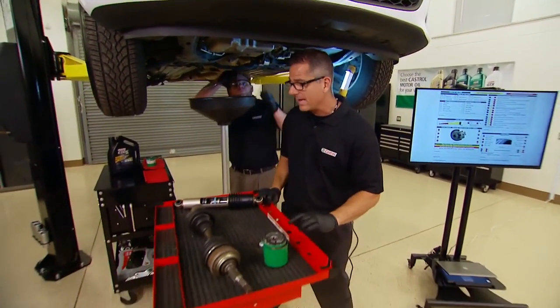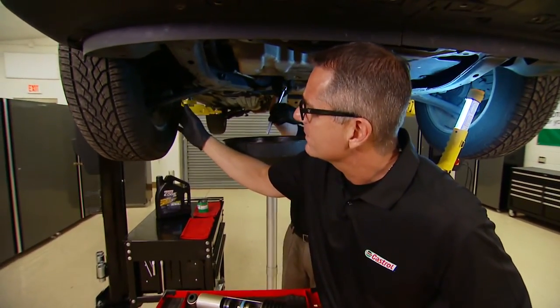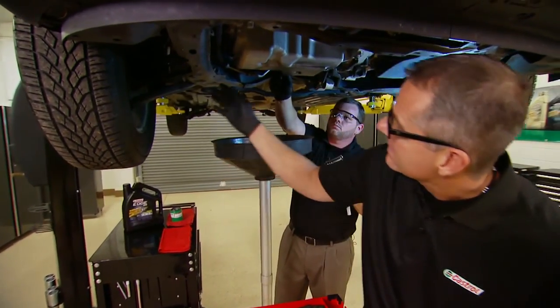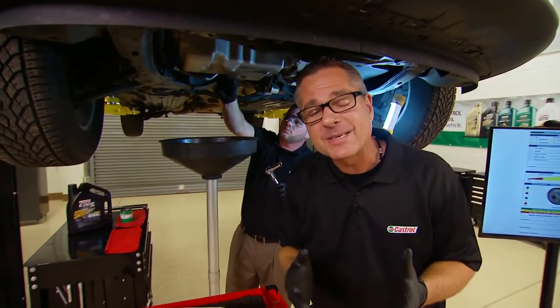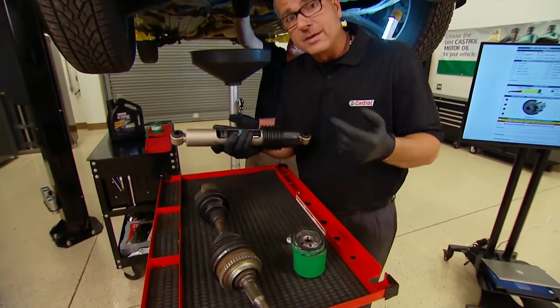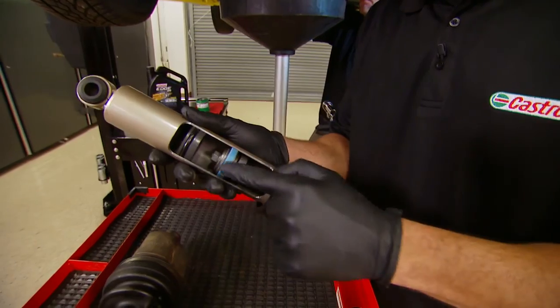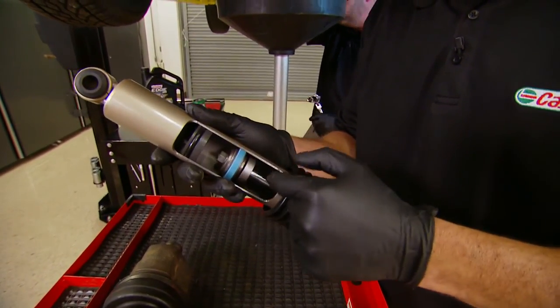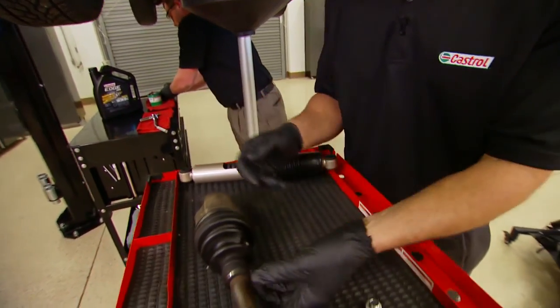We have a few here on the wagon. Take a look at the CV axles, the struts, the components, the shocks, whatever's under here. Look at the ball joints. Like Chase said, check for any oil leaks, motor mounts. They took it to you because they expected professionals working on their car. Now, when you take a shock absorber, just look at it. It may be leaking externally. You can also do a jounce test. These things go up and down and they may leak internally or externally. They may rattle inside.